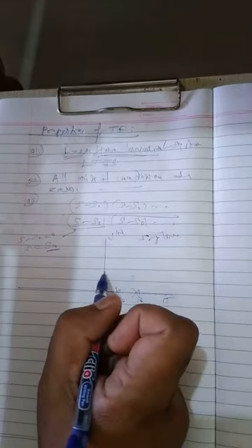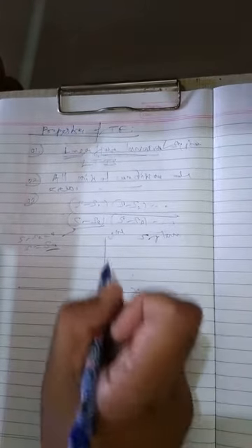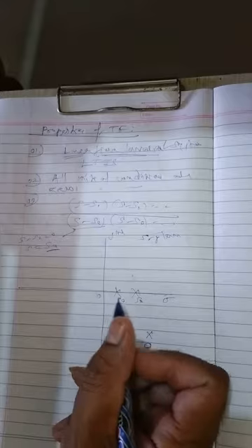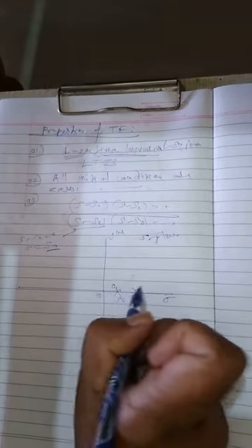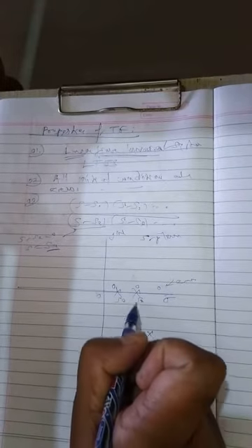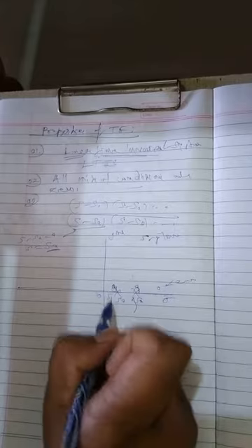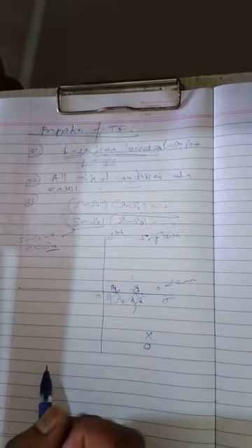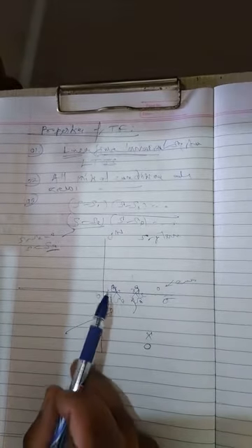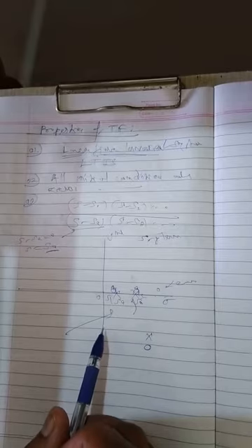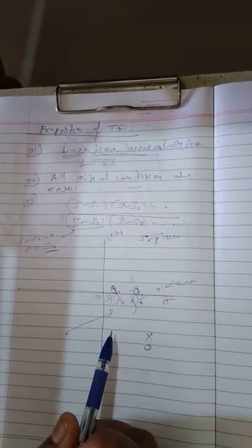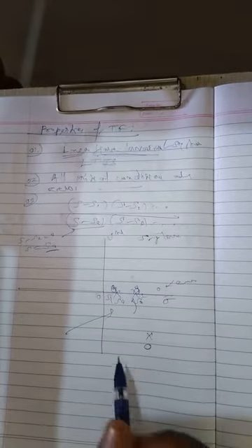Similarly, s minus s1, so s is equal to s1, s2, s3. These s1, s2, s3 are the zeros and these are the poles, whatever the value. So this is called the representation of poles and zeros on the s plane. So what is this property? The system stability can be described in terms of the location of roots of the transfer function.